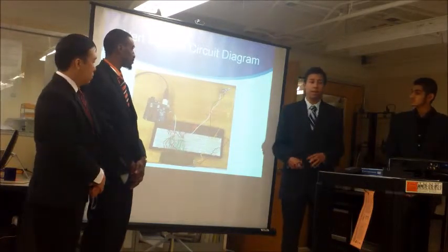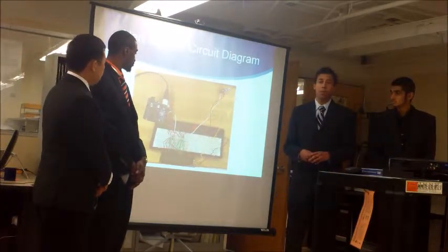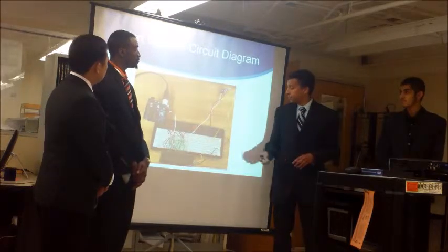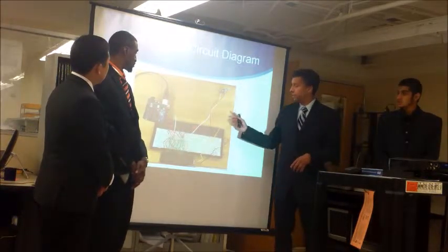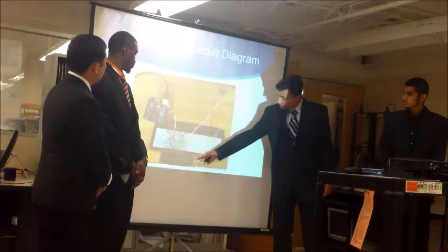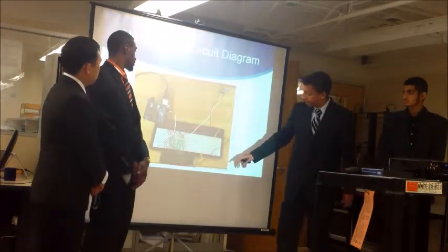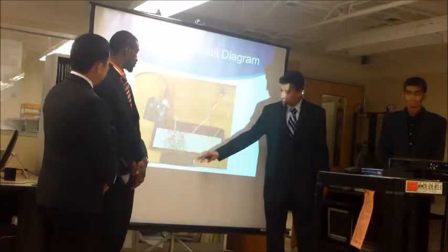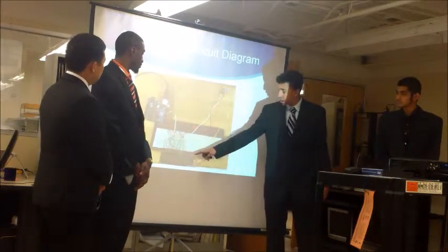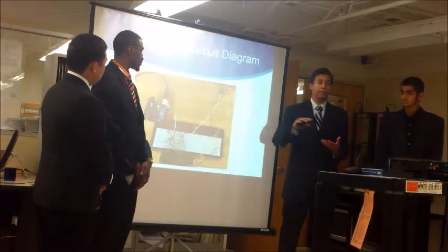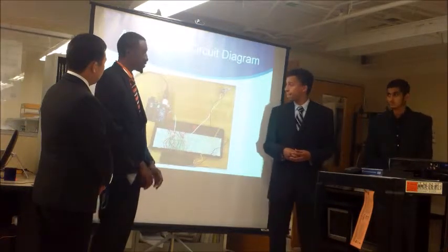This is our current alert schematic that T and I came up with for the analog portion of our project. We have 2 potentiometers here to control the backlight and contrast of the LCD display. What we're going to show you later in our demonstration is how we display that the driver becomes distracted, and it scrolls across the screen.